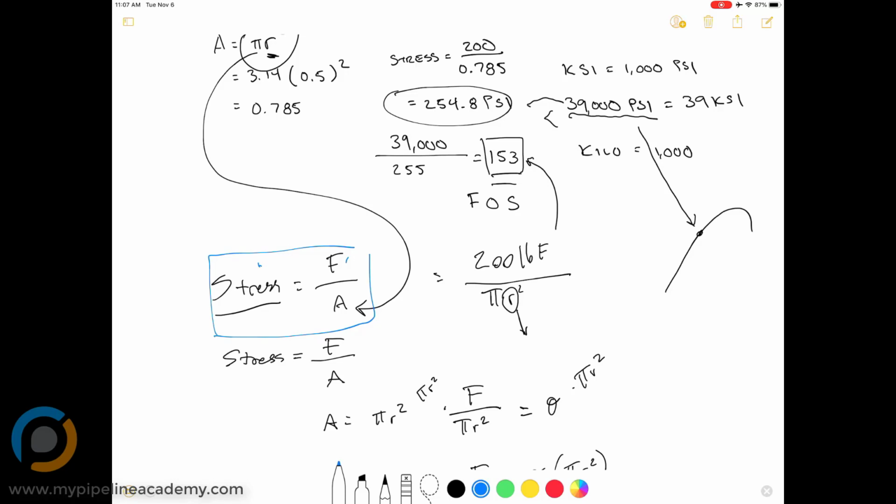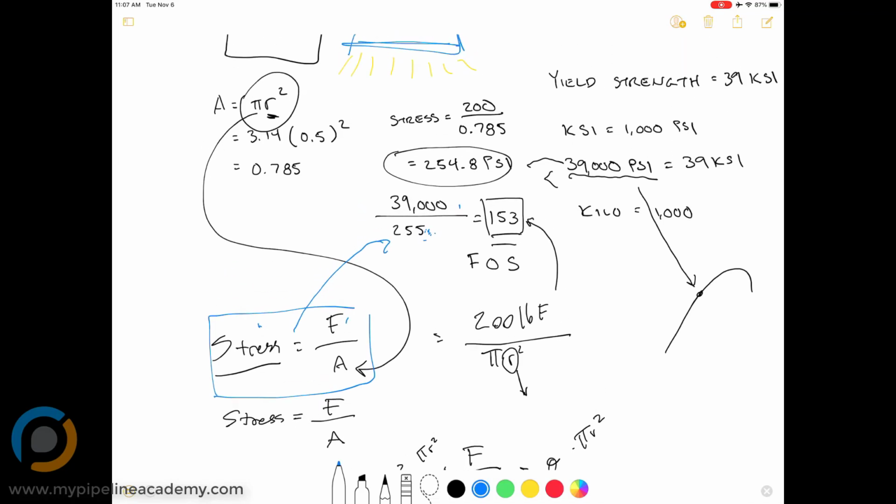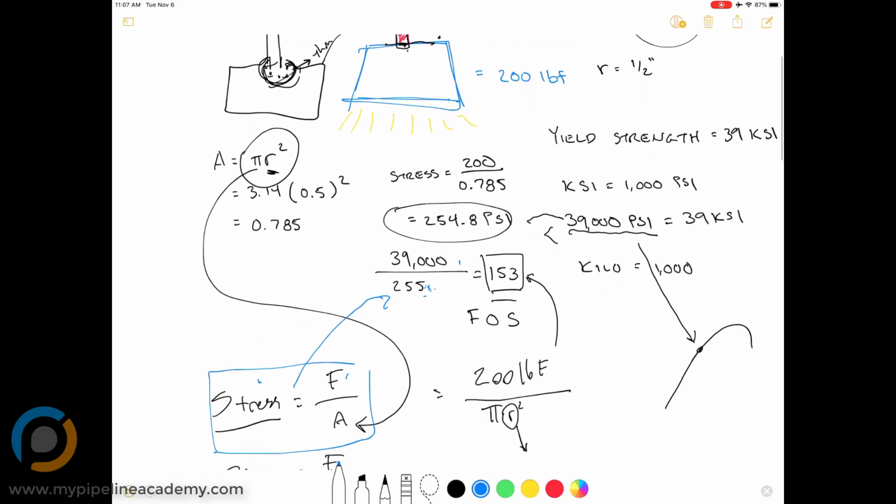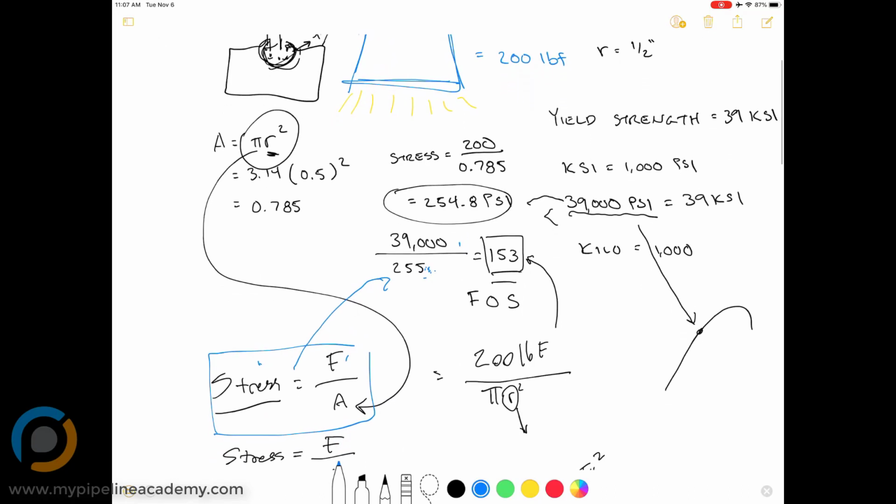So we're going to be dividing this same number, because it's the same material, by this was the stress. So will this number be bigger or smaller? That's the question. Well, what you're looking at right now is factor of safety. I'm just talking about stress. So this boxed in blue here. But the stress is plugged here, right? No. Well, what was the stress? We're not even there. I'm just saying, look at this equation boxed in blue, just looking at the stress value, not even looking at factor of safety at all. If you used the area of a hollow tube as opposed to the area of a solid rod, higher stress. Higher stress, yeah. Right? So smaller cross-sectional area, higher stress. And like intuitively, does that make sense?